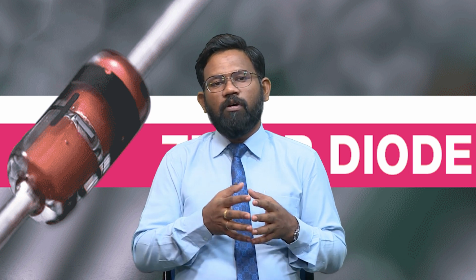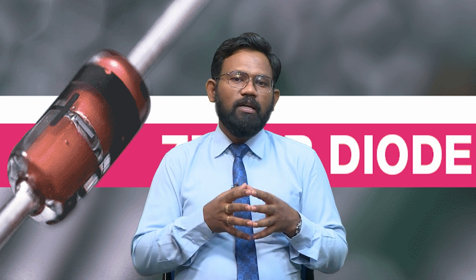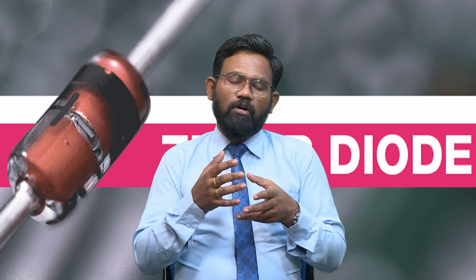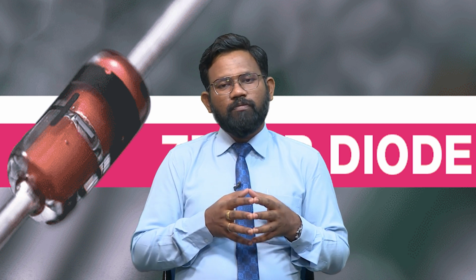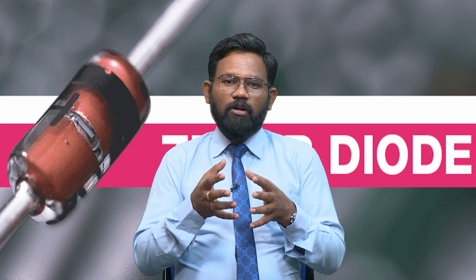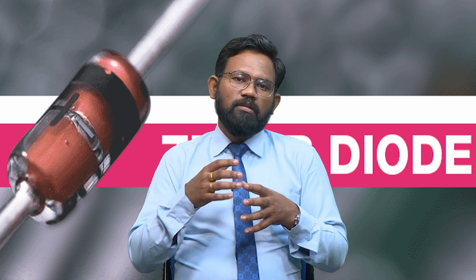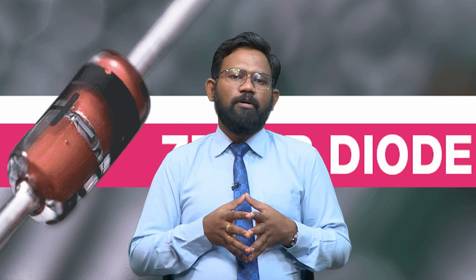So, the Zener diode finds its application in clipping circuits. Suppose an AC current is given to the Zener diode in a particular diode circuit, we can obtain a certain part of it at the output. That is done by the clipper circuit.